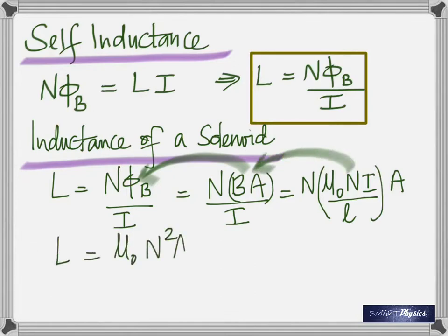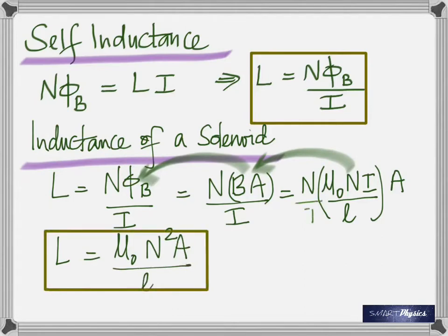Okay, so now rearrange that equation, and you get the formula for self-inductance of a solenoid. That's the formula for self-inductance of a solenoid. What is in the core of the solenoid? What do you have? You have that coil, right? What is it wound on in all these equations? Actually you have nothing. It's just air, free space. That's why you have, what's this? Mu naught.